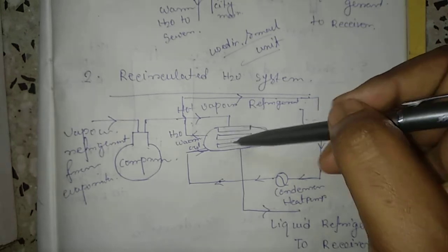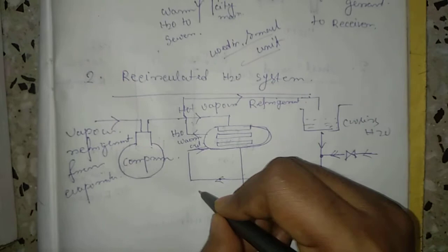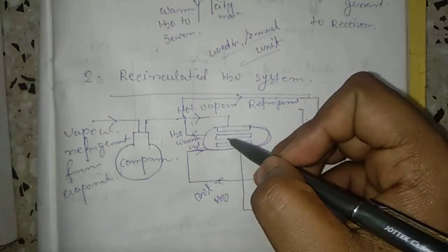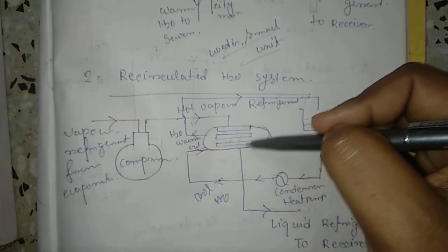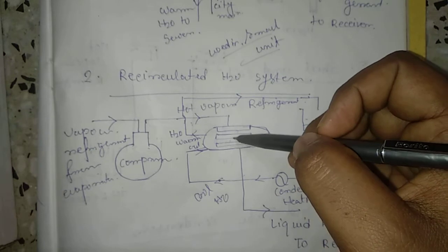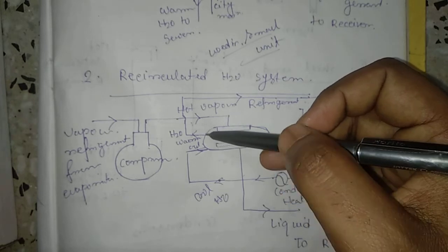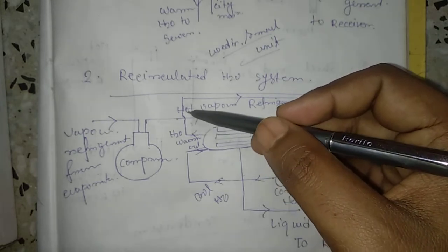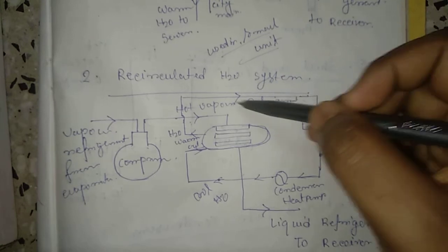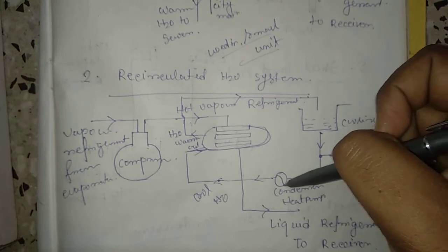Beside the condenser tubes, cooling water enters the condenser, where the cooled water contacts the condensing surfaces, the copper tube surfaces. The refrigerant rejects heat to the cooling water, and the warm water exits from this section and enters a cooling water tower. After it is cooled there, the water flows again into the condenser to cool the refrigerant.